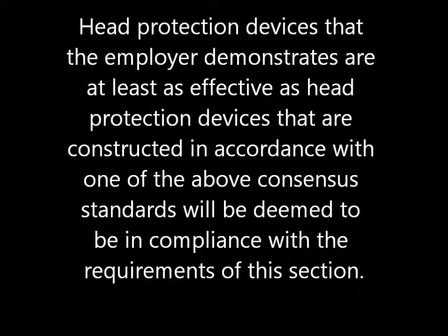ANSI Z89.1-2003 and ANSI Z89.1-1997. Head protective devices that the employer demonstrates are at least as effective as head protection devices that are constructed in accordance with one of the above consensus standards will be deemed to be in compliance with the requirements of this section.